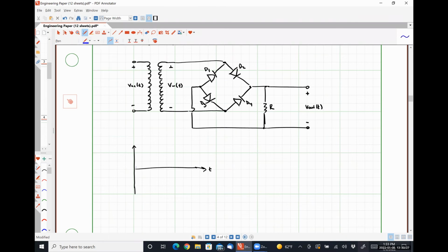So my input signal in blue, as per usual. All right, and we'll talk about what's going on. So let's start with an input signal of 0. What do we think should be happening to literally all of these damn diodes if our input voltage is 0? Yeah, so all of the diodes are off. So there shouldn't be any current flowing through our resistor R. So we shouldn't be generating any voltage drop across our resistor, okay?